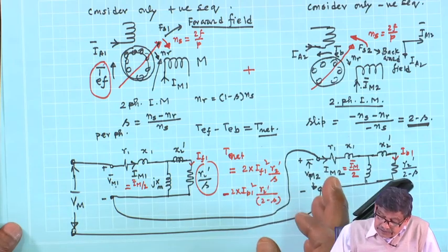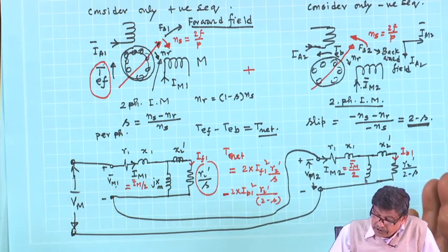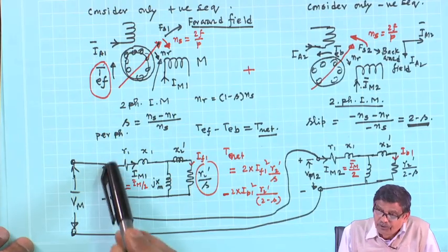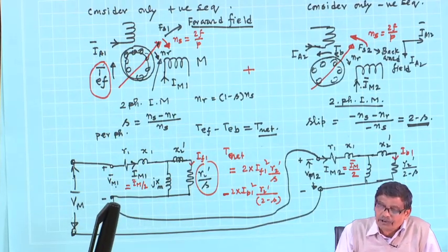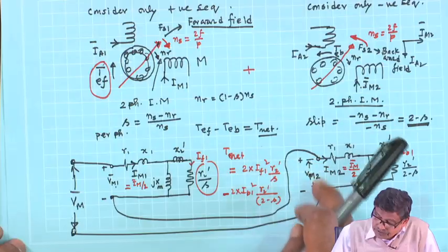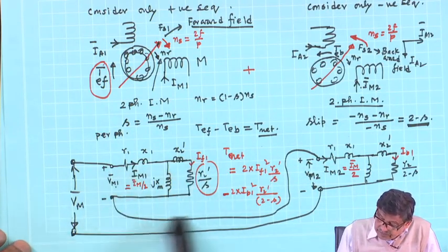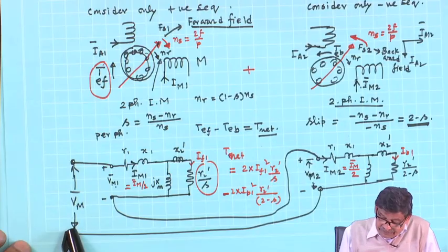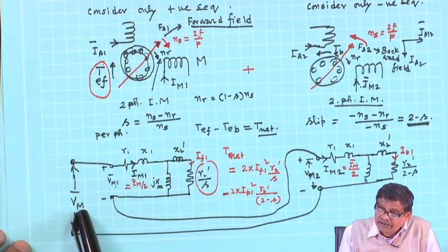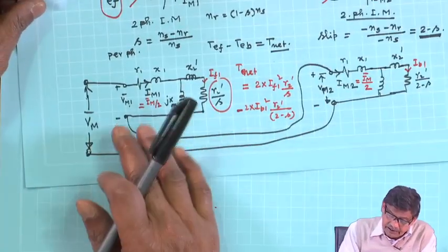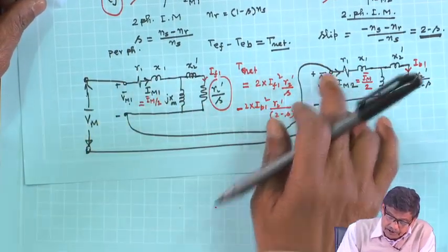And then I know IM1 is equal to IM2, and this voltage here will be the positive sequence voltage of M1, this is the negative sequence voltage of M. Therefore, why not connect them in series, and it will be like this. Now this voltage is Vm1 and Vm2.